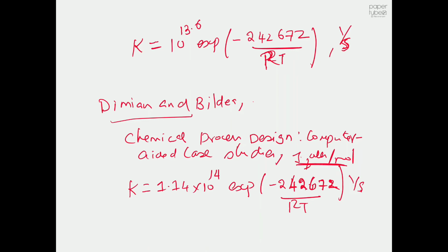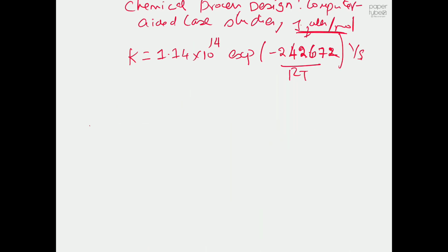And we also have the rate expression for all these three reactions. From the pyrolysis chamber we put in ethylene dichloride. After pyrolysis we will get a product stream that should contain vinyl chloride monomer plus some impurities.